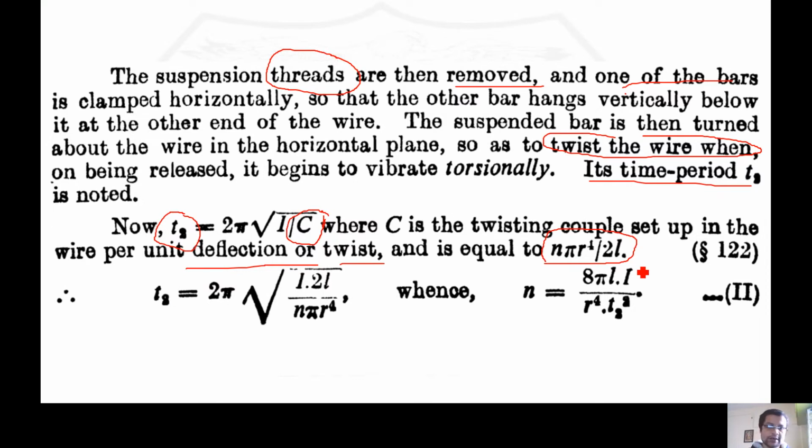Why is it eta in this case? Because the forces you apply are tangential to the direction of the twisting. So shear forces are developing inside the wire, and you have the corresponding shear strain. That ratio gives me the modulus of rigidity, eta, and that is why this particular eta comes here. So instead of Y, your expression contains eta, and this eta is the modulus of rigidity.